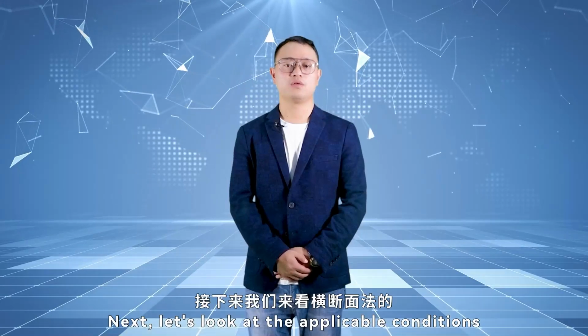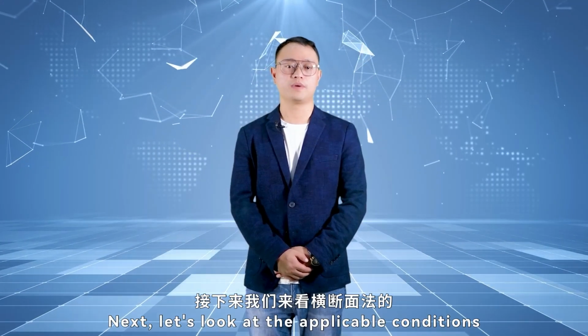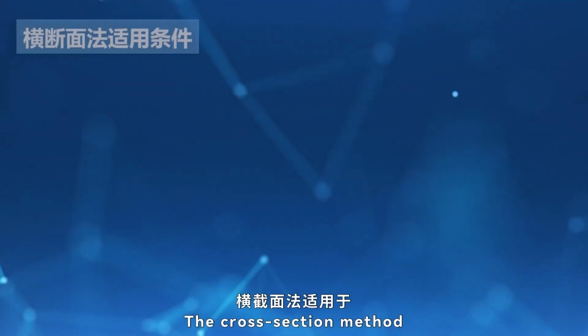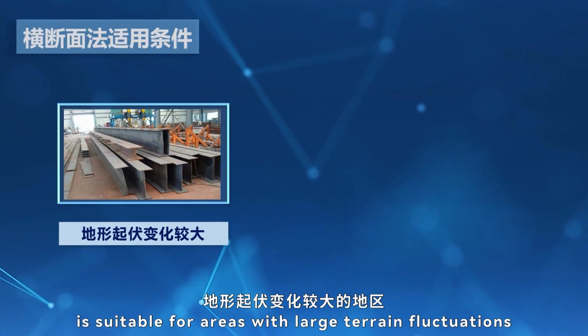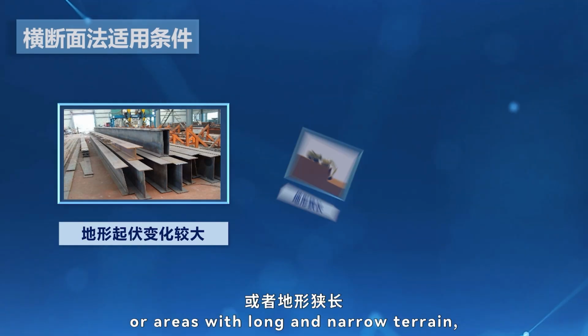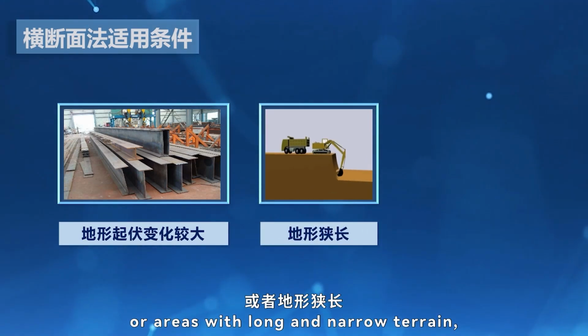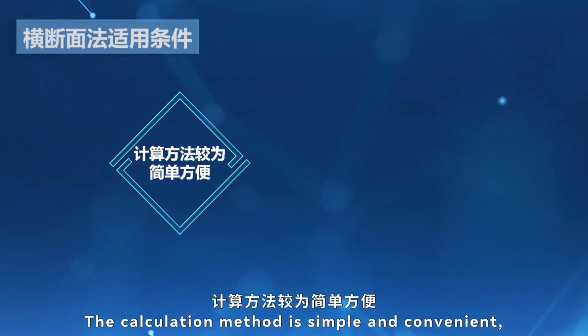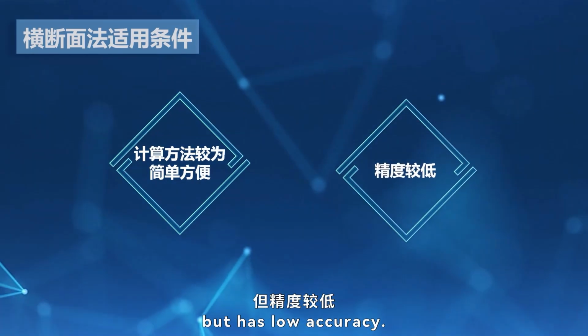Next, let's look at the applicable conditions of the cross-section method. The cross-section method is suitable for areas with large terrain fluctuations or areas with long and narrow terrain, large and irregular excavation depths. The calculation method is simple and convenient, but has low accuracy.